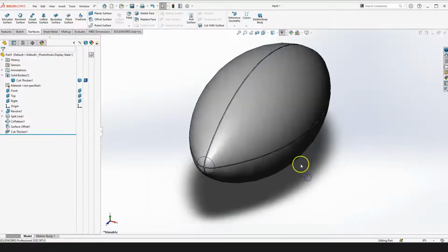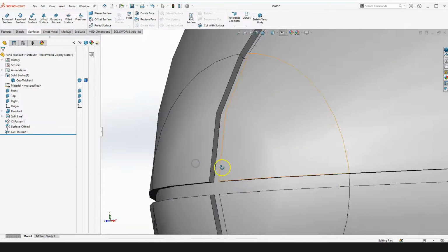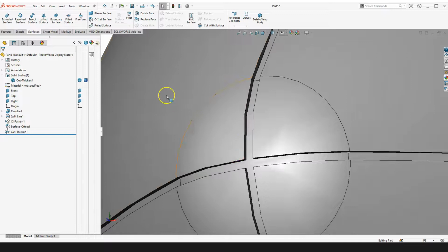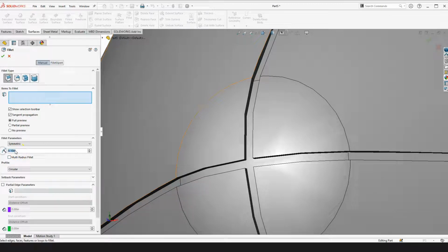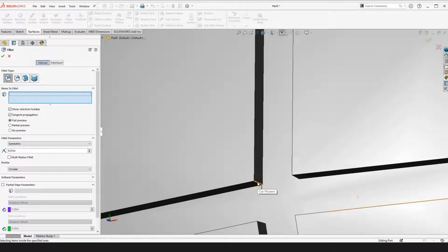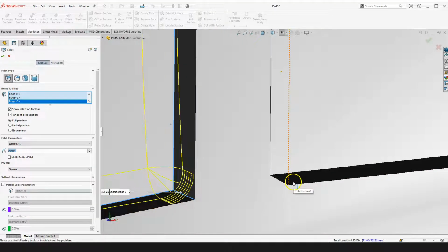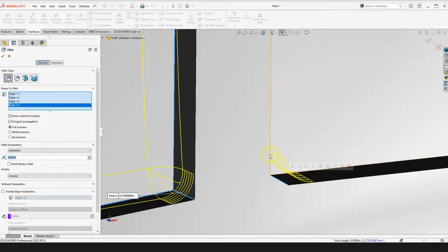So next, what I want to do is add some fillets to these sharp corners. So what I can do is up here, go to fillet, give it a small dimension, like a 0.01 there, and I'll start clicking on the lines there. So click on that line. That is just pretty much go around and pick all your outside edges on those cutouts. I'll do that here.